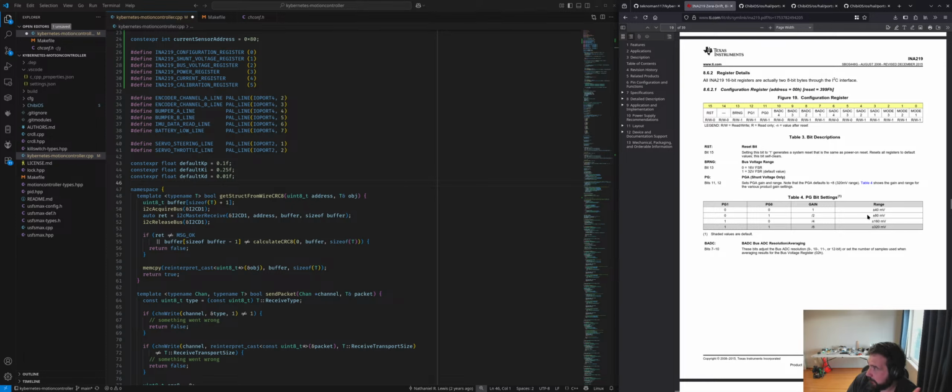So if you were to, say, integrate a battery charger, the typical system architecture for this current sensor is that you'd basically put the battery, you'd put the current sensor, and then you could have, in parallel, your device and then the battery charger. And if the current is negative, you're charging the battery. If the current is positive, you're draining the battery. Well, it really depends on which way you hook up that shunt resistor. I'm pretty sure that a positive... yeah, I think it's right. I think positive is going to be draining the battery, negative is going to be charging the battery. But either way.